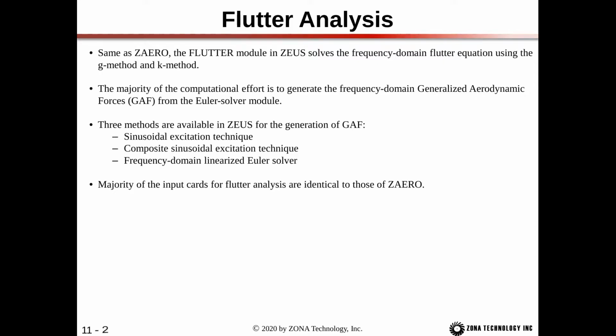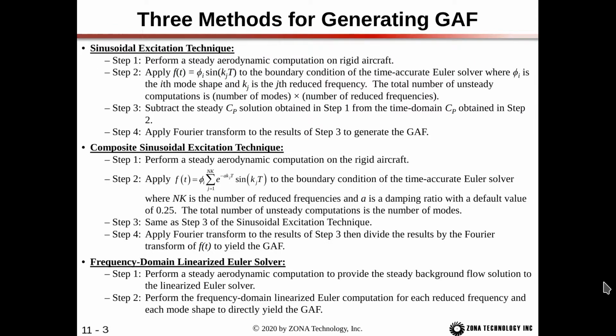The first is the sinusoidal excitation technique. Next is the composite sinusoidal excitation technique. And then finally, the frequency domain linearized Euler solver. And we would recommend using the frequency domain linearized Euler solver. And the majority of the input cards for the Flutter analysis are identical to those of ZEUS. So the three methods in detail.